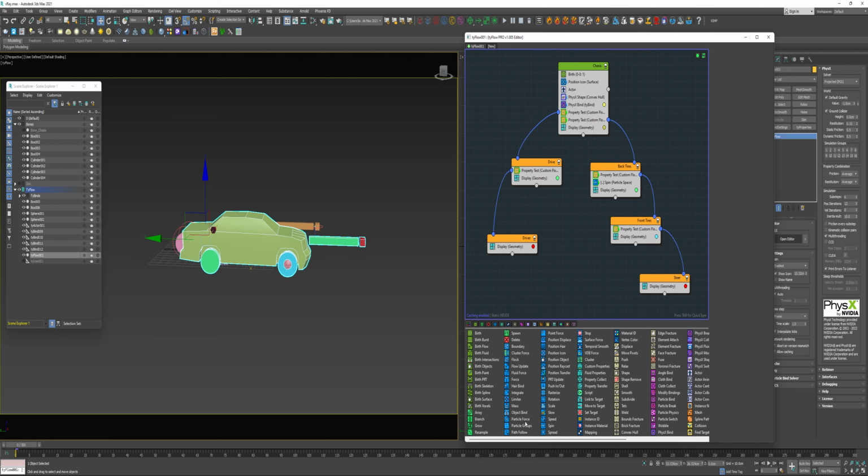I'm going to add a particle groups into the chassis event beneath the actor. I'm going to enable group 1. I'm going to add a particle groups to the driver event, and I'm going to place that on group 2. And next I'm going to add a rotation to the steer event. I'm going to change the orientation to align to neighbors.